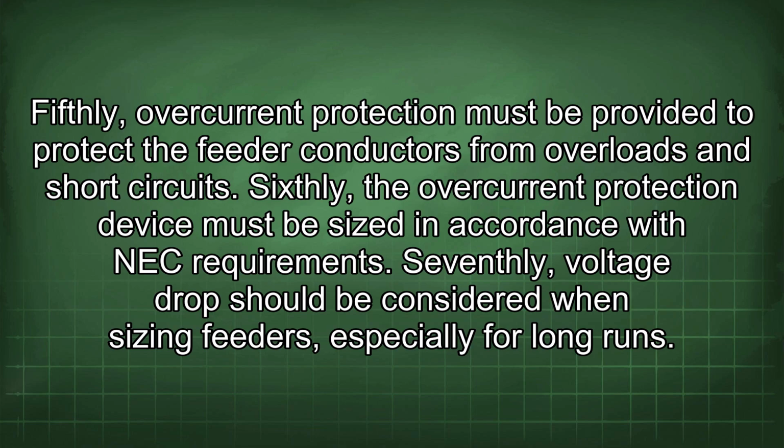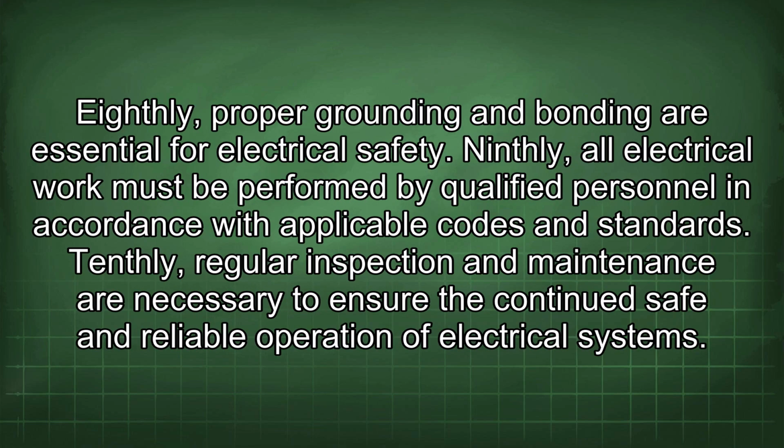Sixthly, the overcurrent protection device must be sized in accordance with NEC requirements. Seventhly, voltage drop should be considered when sizing feeders, especially for long runs. Eighthly, proper grounding and bonding are essential for electrical safety. Ninthly, all electrical work must be performed by qualified personnel in accordance with applicable codes and standards. Tenthly, regular inspection and maintenance are necessary to ensure the continued safe and reliable operation of electrical systems.